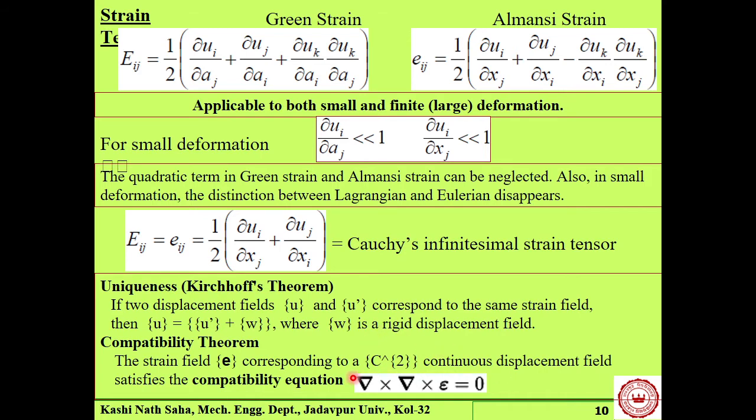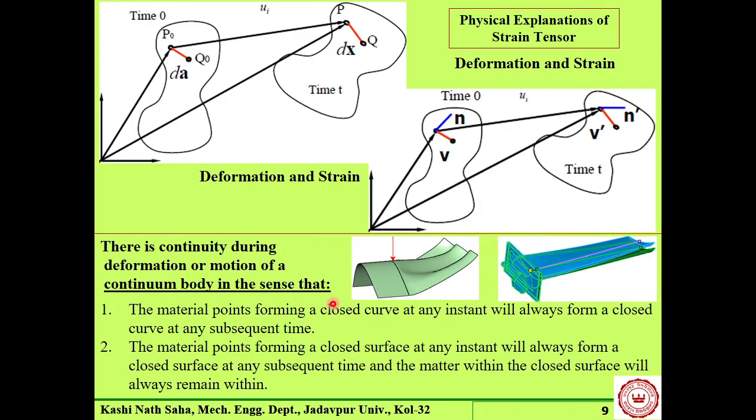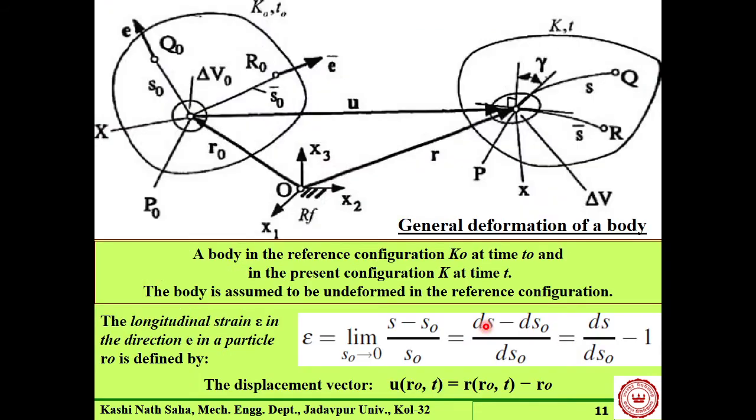So these are some conditions for our discussion within the continuum mechanics domain. Now this is the general description. How do we measure? We measure a line element, the change in length of the line element. This is a phenomenon in 2D, right? And in addition, we measure the change in the right angle between two reference lines.